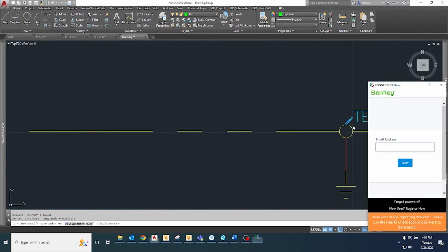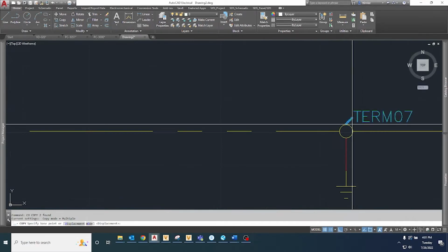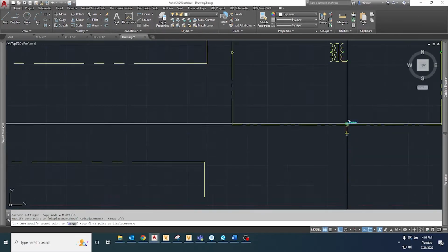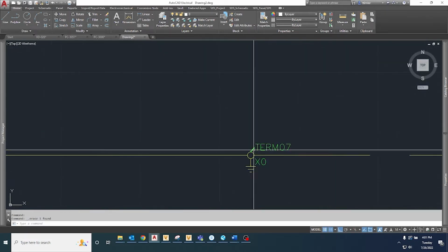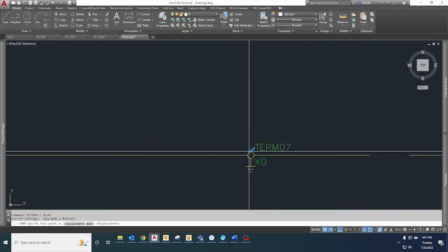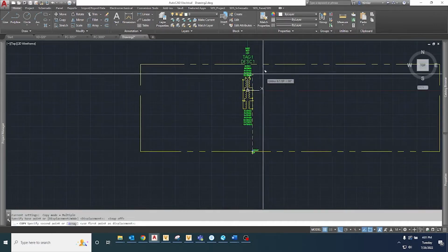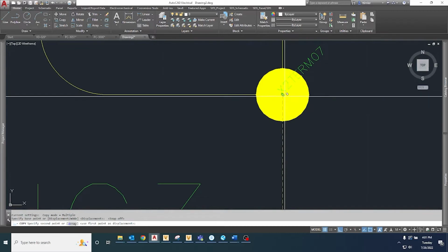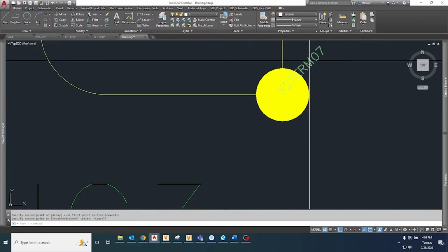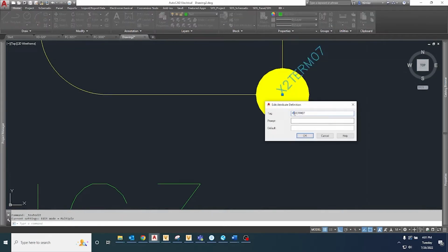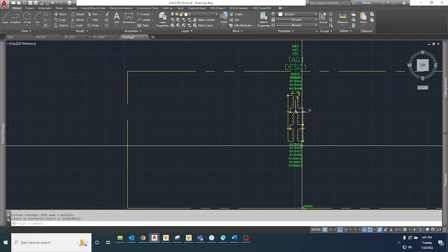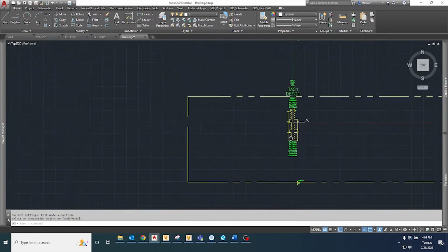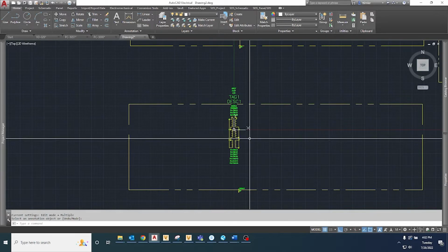There's going to be a wire that connects from the lower transformer winding to this terminal that is going to contain CTs. So I'll copy this connection point attribute up and place it on the lower winding. And then I'll rename that from X2 to X8 because wiring is going to come into this winding from below the connection point. Of course, I need to go grab the supporting attributes for the symbol from the one-line template and move them over.